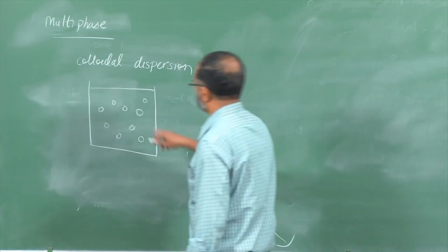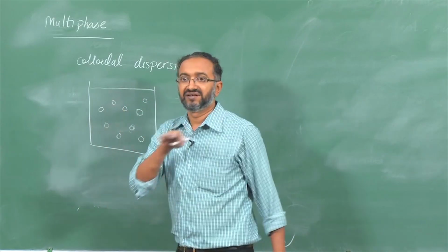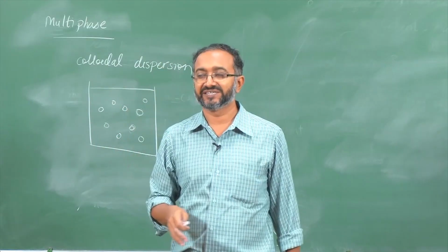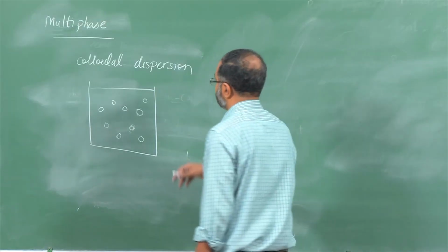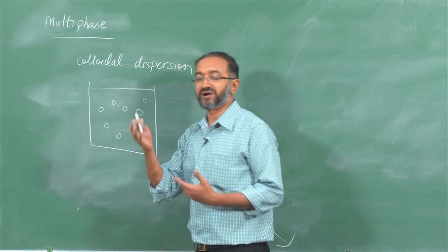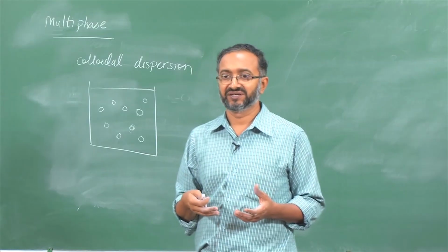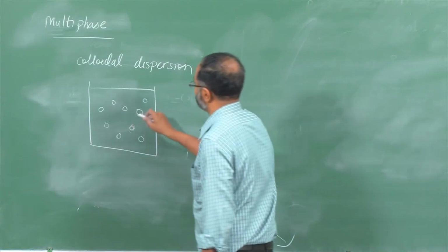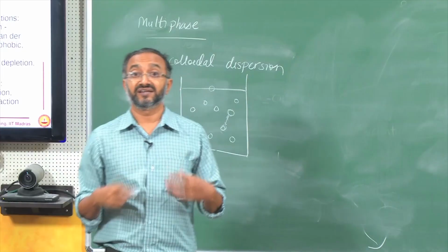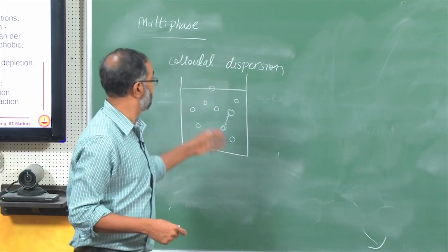So, there is the Brownian force, which means that even if this is stagnant, the particles will undergo Brownian motion because the solvent is randomly bombarding these particles, and that is the Brownian interaction. If we put this in shear and therefore force these particles to move, then there will be drag exchange between the particles and the surrounding fluid, and then finally if there are too many particles, the disturbed flows will interact through hydrodynamic interactions. So, clearly, let us say if in some application I am interested in not the bulk response.